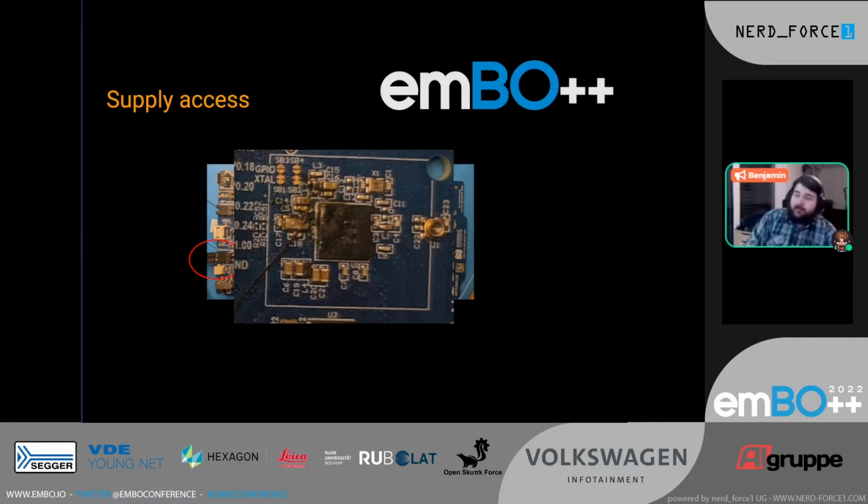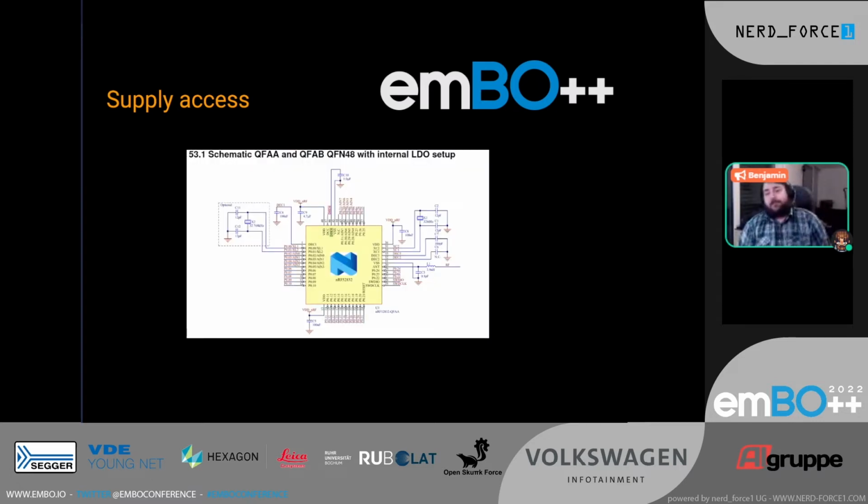As you can see, it is nicely separated from everything else, and there are a lot of components that deal directly with this chip. And one thing you should know is silicon vendors usually provide you with some schematics and reference designs for the power supply of their chip. In general, system integrators do not deviate from this, because if they do, the question becomes, did we screw something up with our design, or is the chip faulty? And of course, the silicon vendor will point at, well, you didn't follow the reference design, good luck figuring it out.